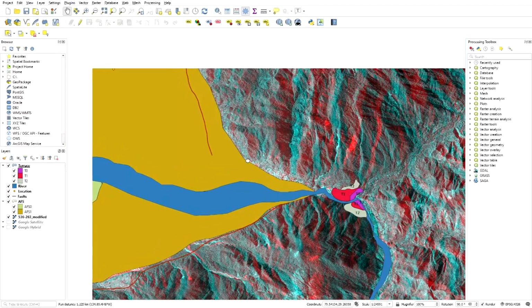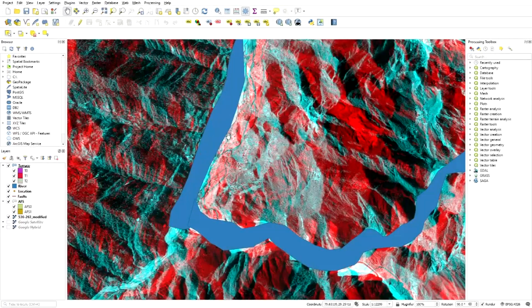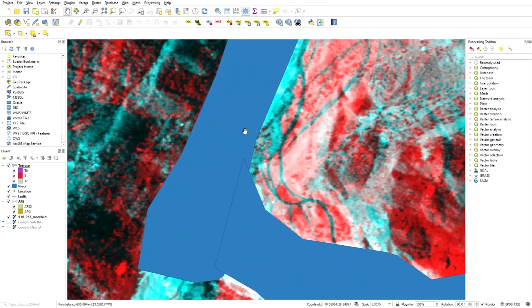In this lecture we will also demonstrate how you can use these vector files or vector layers to make your vector layers more precise or enhanced. Here you can see these two vector shape files, and you can see the boundary line clearly. You have to dissolve this line or remove this line, which you can do simply using your symbology options.